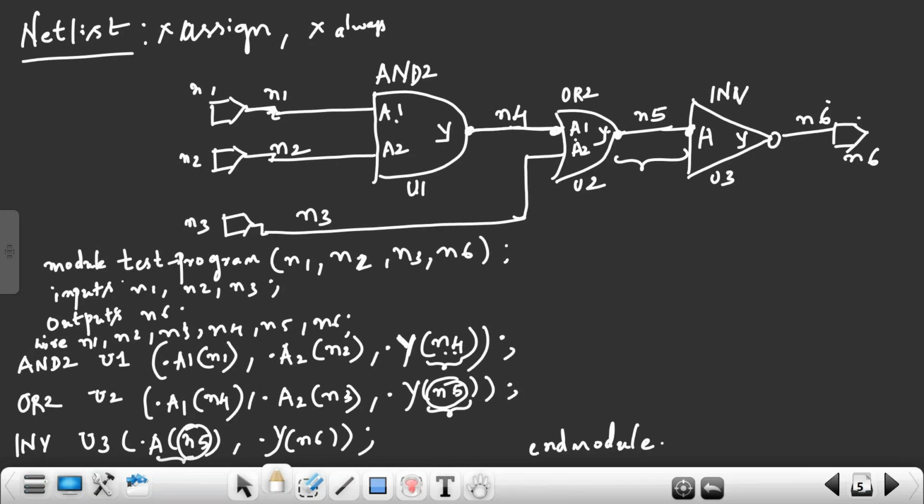That is called physical. The gates, which we have as symbols or descriptions, convert into layout format. For a gate, physical format means layout. For a net, physical format means a metal layer. That is called physical design.